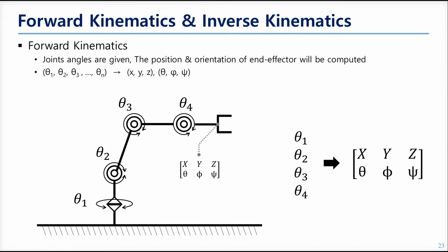This is the forward kinematics. If the value of every joint is given, the forward kinematics will show where the end effector is in the XYZ coordinates, and the orientation also. Forward kinematics is very simple. Imagine that you bend every joint of your arm, each at a specific angle, and see where your hand points. Now you will notice that your hand will point in only one direction, and there are no more directions that can be pointed if all your joints are fixed in that situation. In other words, you can get only one value in the calculation.